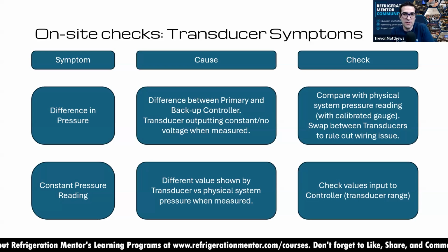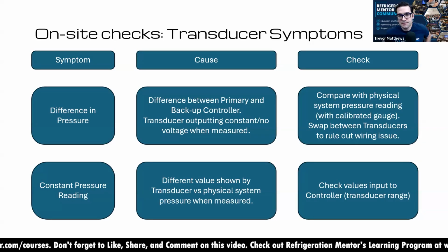And then, like you said earlier, Chris, I really like that point. Is that the right transducer? Is that a 0 to 60 bar transducer, or is that a 0 to 30 bar transducer, and it's not getting the proper range? And so now that valve is working way erratic. It's still maybe working a little bit, but it's not reading correctly. So the range is off. Right.